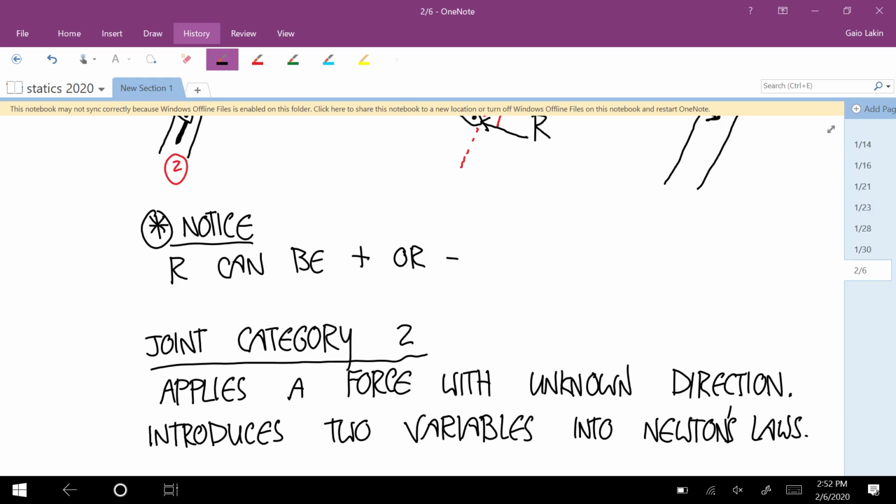It's not about whether you're clever enough. There's no way using statics that you can use 3 equations to solve for 4 variables. So when you look at problems, a lot of times, at least simple problems, you can count up how many variables are going to get introduced and how many equations you're going to have. This is going to work or this isn't going to work.